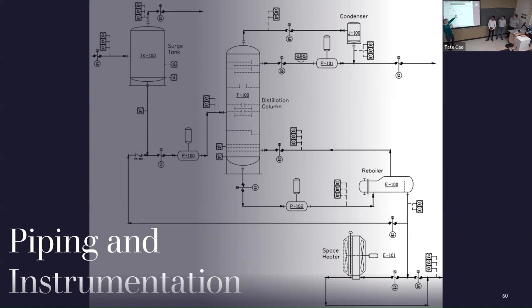In this case, the water settles into the bottom here. The liquid water settles into the bottom. It goes into a reboiler where the steam is put back in to maintain a very high temperature at the bottom. In the top, all the gases, these are the unwanted gases, go through a condenser, are cooled, and then put back in here to maintain a cool temperature at the very top. Some product is taken away, and that's how you get our separation.